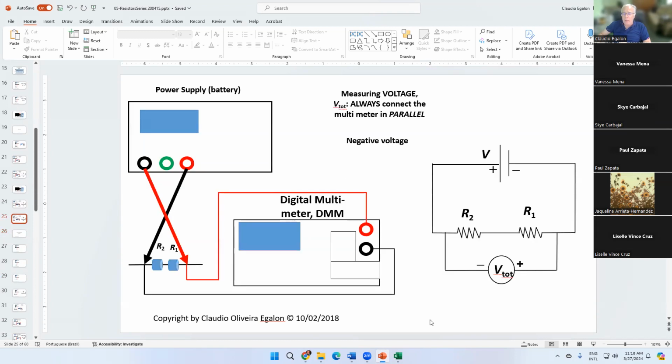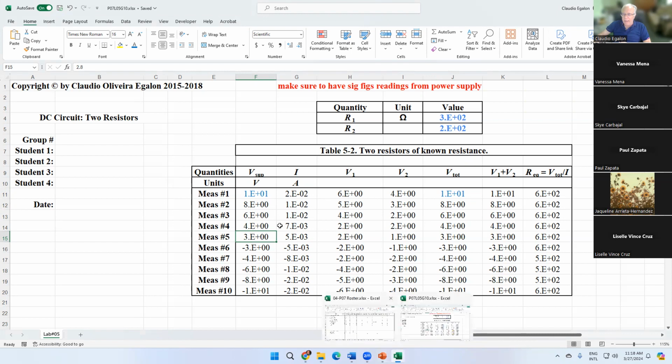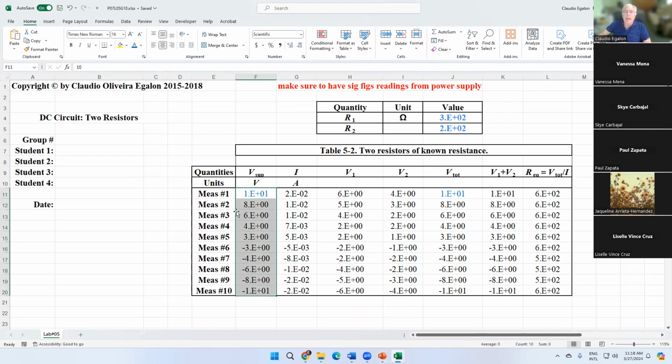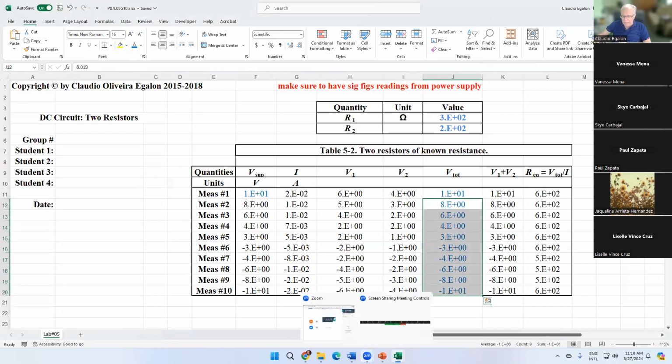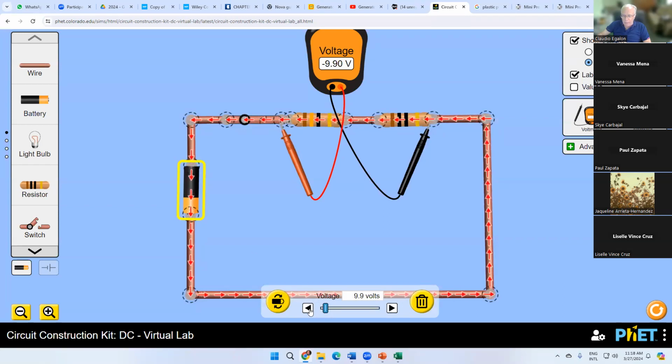We're going to measure. And by the way, there's more to that because we have to change the voltage. We did for 10 volts. We're going to do for 8, 6, 4 and 2.8, right? Invert everything and measure everything. Going back to 8 now, okay? Whatever I set here as being 8 volts, that's what he measured, right? You do that for positive and negative.